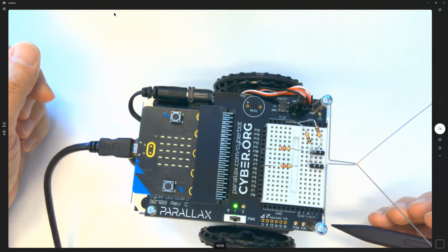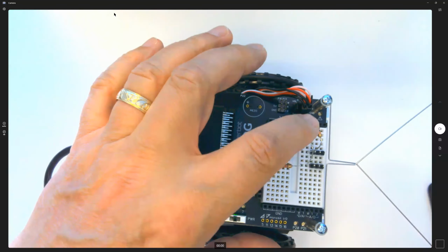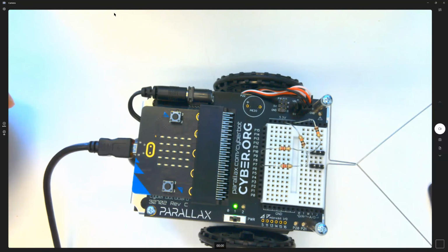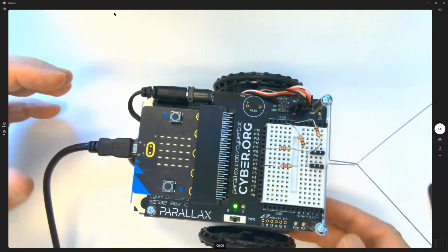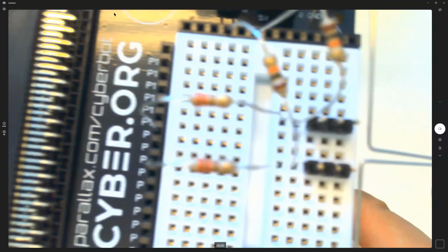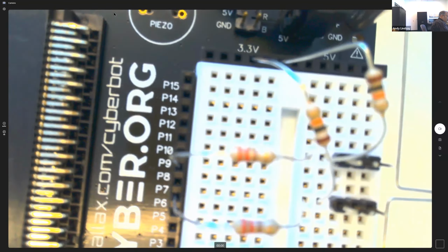And we also have from John, I can't get mine to work. I've done the circuit twice. So this is making me wonder about double checking the rows that the resistors are in, making sure they're in the same row as the 3-pin header, and the correct IO pin holes. Well, yeah, there are a few common errors.